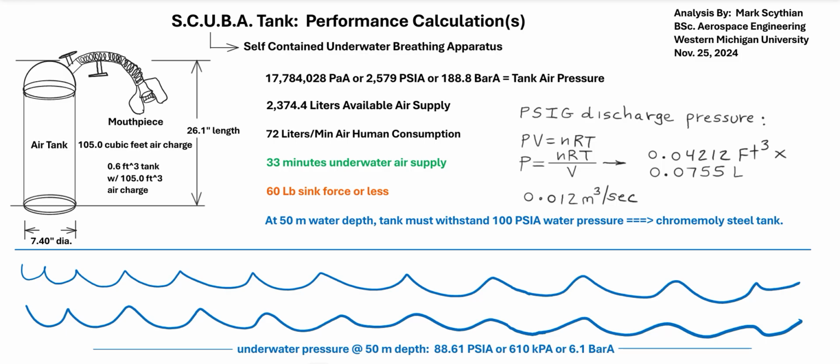And so if we take the cubic feet of charge with respect to the weight of that charge per second, it's going back to the 0.042 cubic feet per second times the air density we previously calculated. We would then have to discharge 0.0032 pounds per second mass air, and then times 454 grams to a pound.